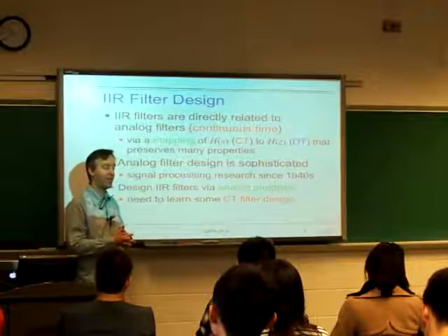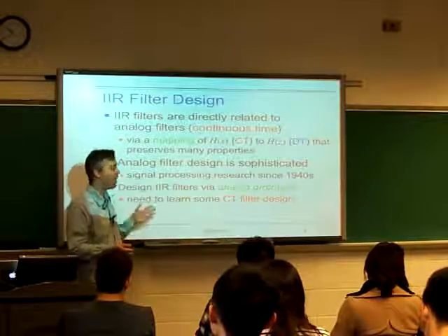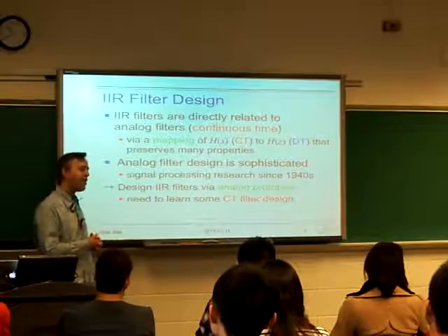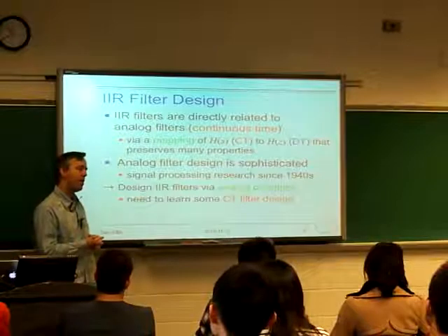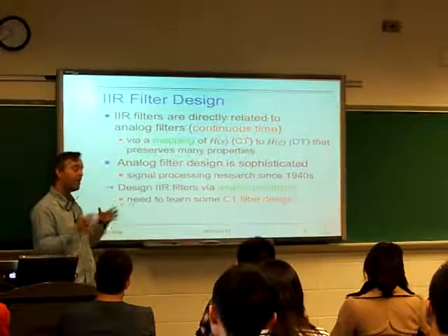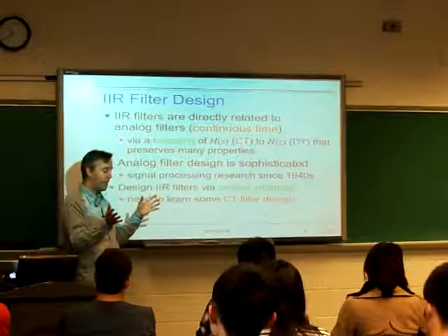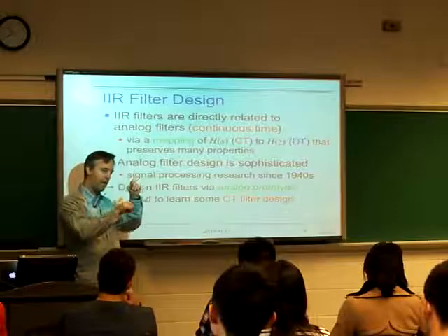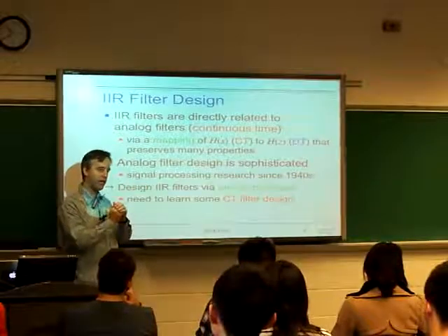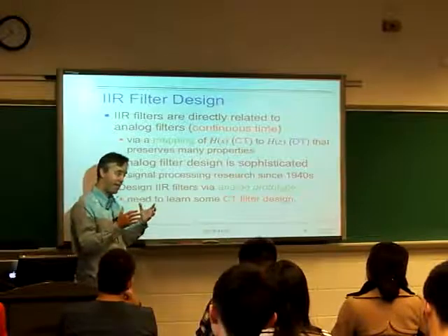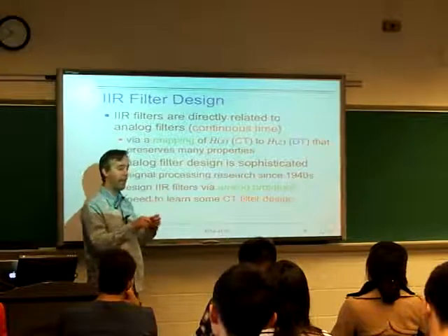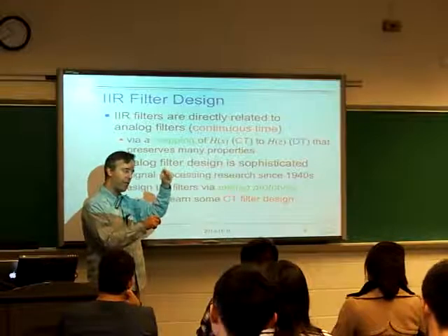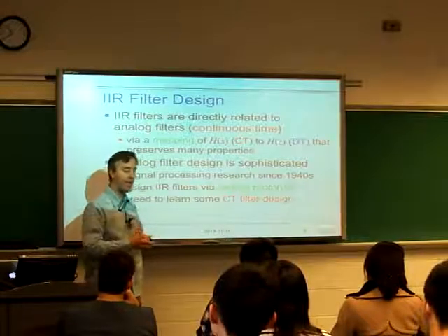And it may be that, as time goes on, the need for IIR filters becomes less and less. But maybe there's another advantage that IIR filters have, because of this whole perspective we've taken of thinking about the performance of filters in terms of where the poles and zeros are relative to the unit circle. If you want to have an actual pass band, some frequencies that you keep, typically that means I'm going to put poles near the unit circle for those frequencies I want to keep. And that's a very natural way to build a bandpass filter.